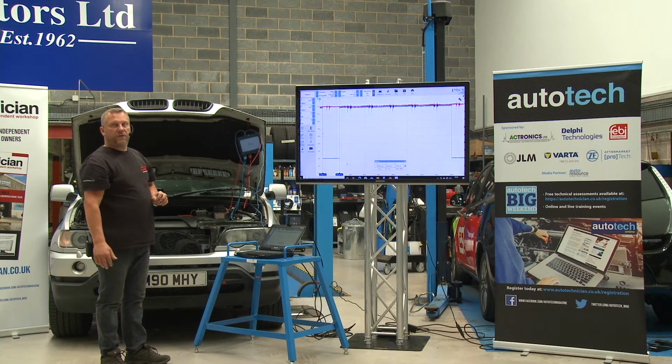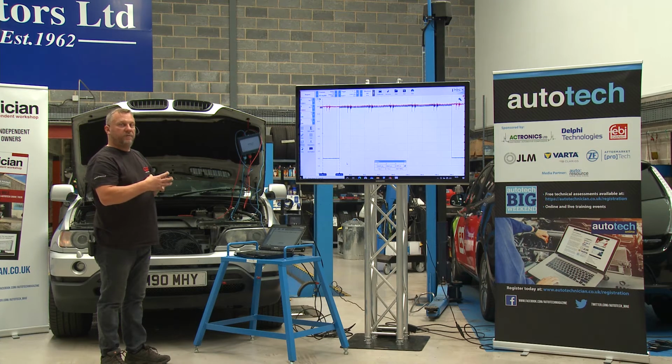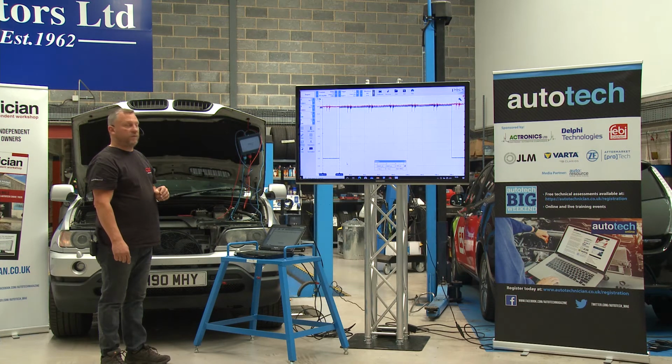So capturing the image in a way that makes it easy to analyse is the job of the trigger. The time base allows you to select how much information you want to look at on one screen at any one time. On images or signals that repeat, having 2 on the same screen at the same time gives you a point of reference. Using the trigger allows you to do that without it dancing around the screen.